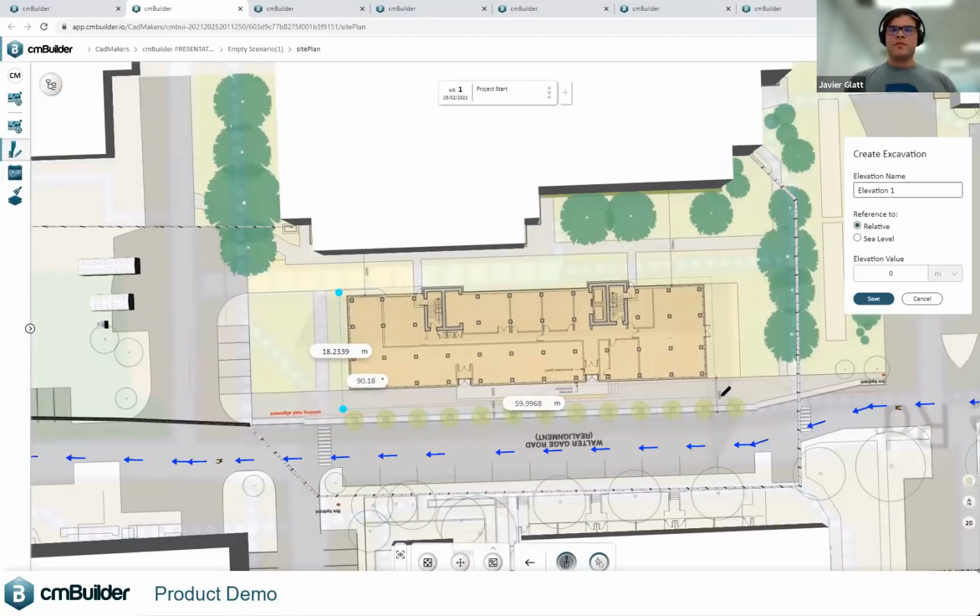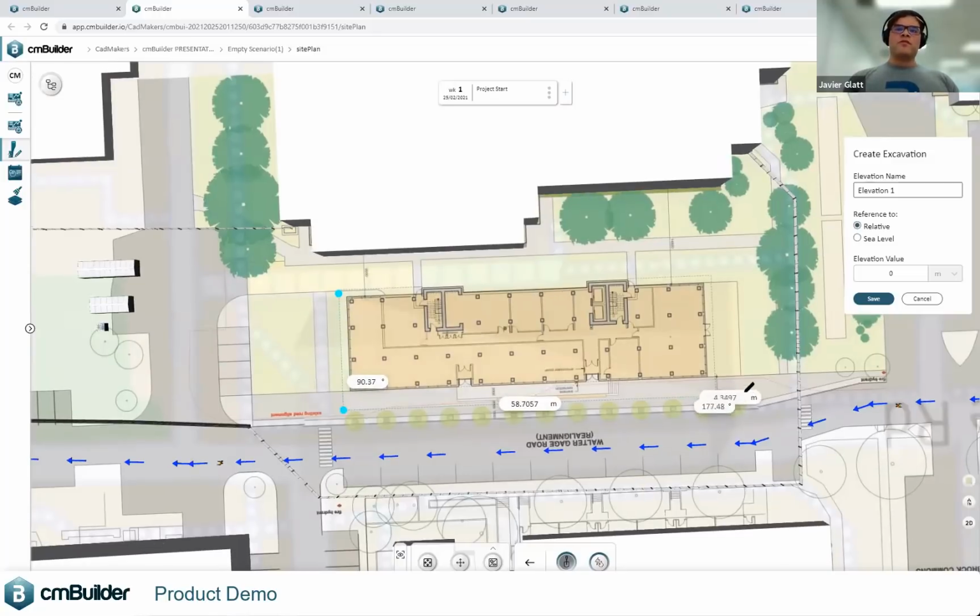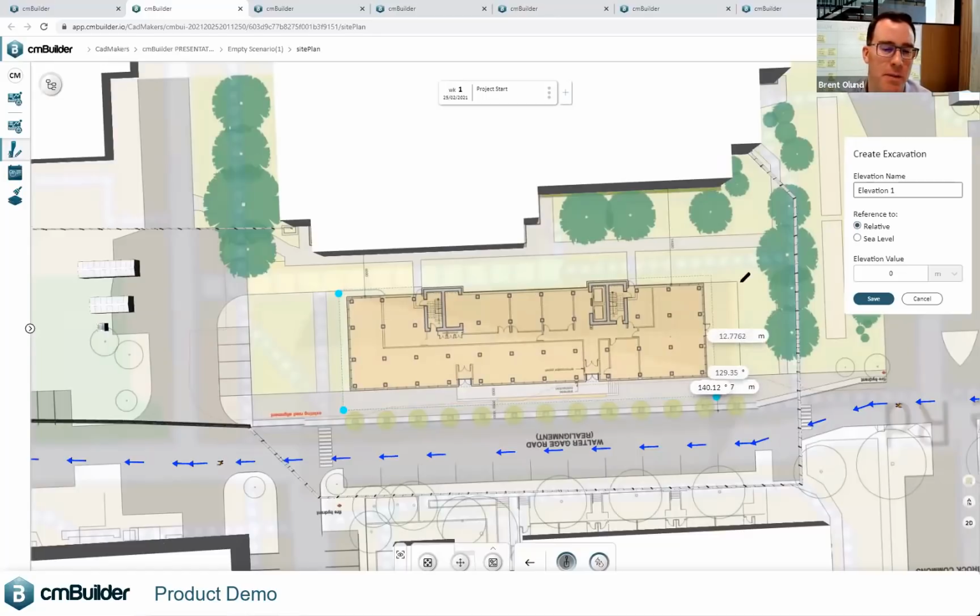I know we spent quite a bit of time in the ground coordinating. How deep roughly was this excavation? It was a pretty shallow one, was it a few meters only, right? There wasn't really a basement, but we had some deep core footings, deep tower crane base, and underground water storage tank. We had to coordinate those things with all of the underslab plumbing.